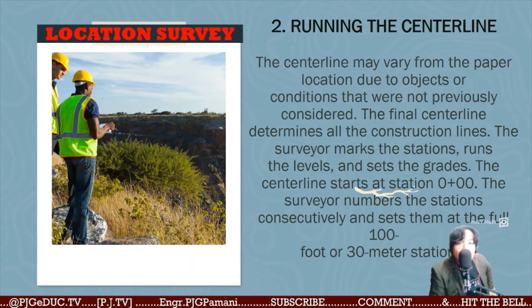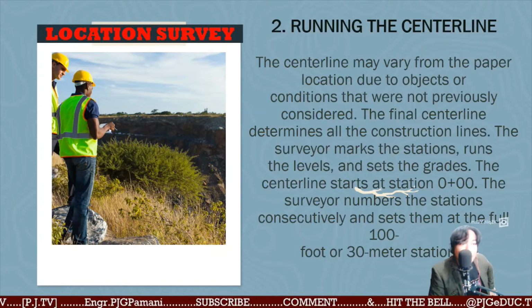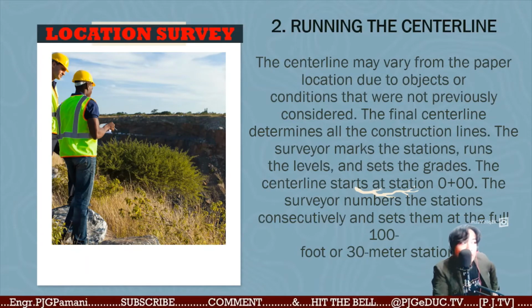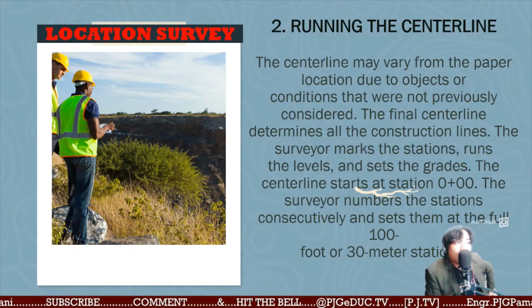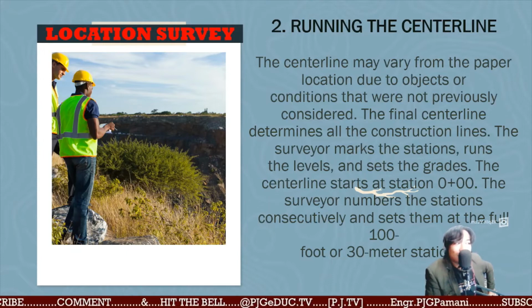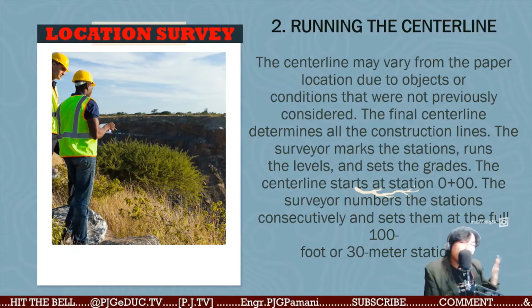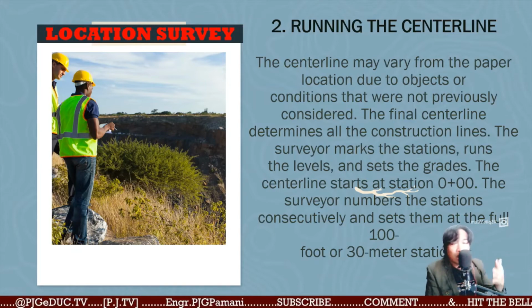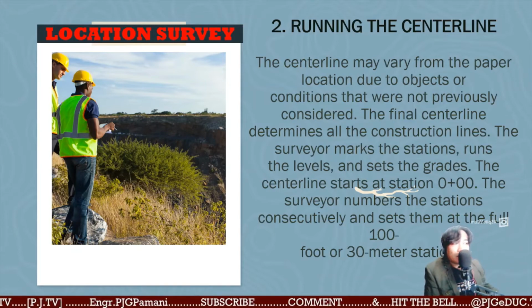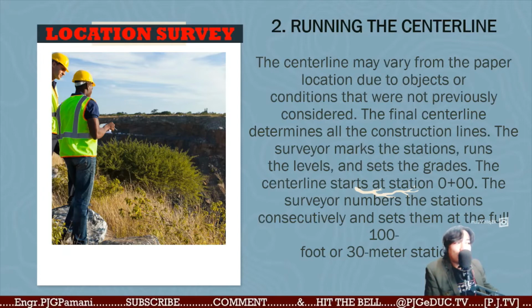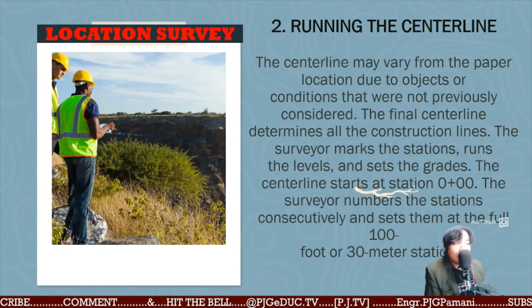Running the center line with the location survey may vary from the paper location due to objects or conditions that were not previously considered. Yung mga hindi natin nakita during our reconnaissance and preliminary survey. The final center line determines all the construction lines. The surveyor marks the stations, runs, and levels.